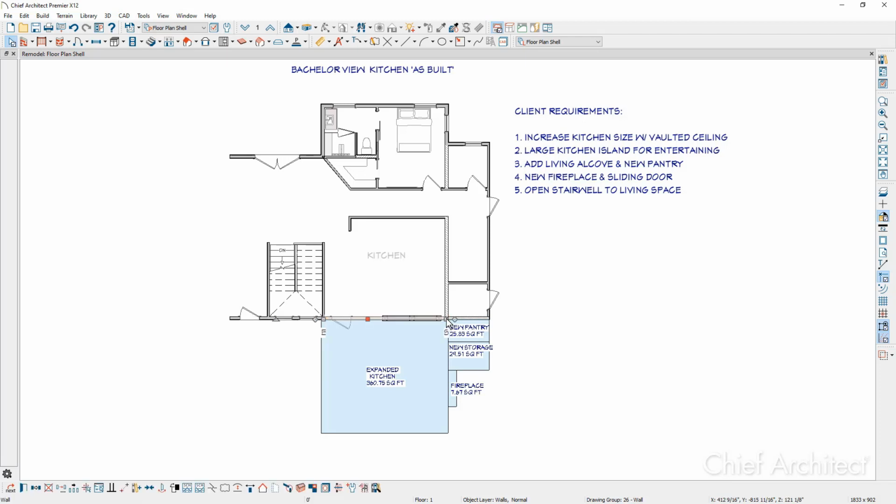Now as I move this wall out, there are some other elements inside of that wall, and I'm going to hold my shift key down and draw a marquee around that entire segment so I make sure I get all of those components. I'm just going to simply pull this down until I get approximately to the outside of this outline. Then I'm going to select the wall, and using the diamond on each end of the wall, that will extend that wall back towards the house.